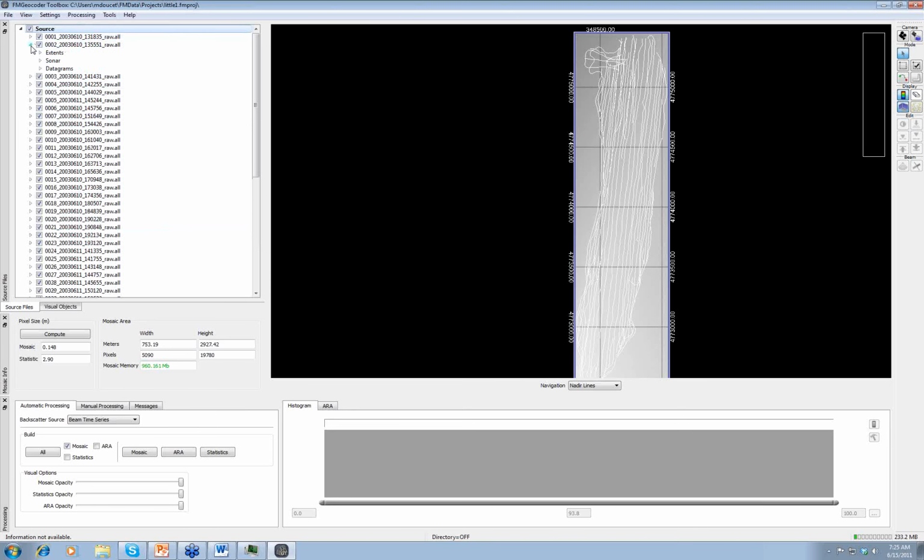This is very similar, but now extended, to what we did with the Midwater tool. You can see all the metadata related to the input files, so the type of datagrams that you have. And this is actually a good debugging tool if you're ever having an issue with a file. You can look to see, does it actually have seabed imagery? Does it have backscatter data? You can also get some information on the sonar type, how many heads there are, what we call the modes.